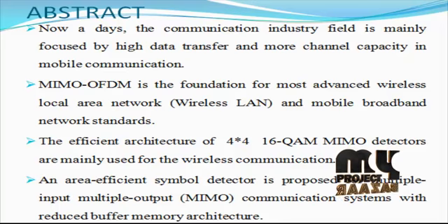Mbps. LTE-Advanced, which is the evolution of LTE, supports single user spatial multiplexing of up to 8 layers in the downlink and 4 layers in the uplink, targeted to achieve peak data rates of 1 gigabit per second and 500 Mbps respectively. SC-FDMA utilizes a discrete Fourier transform spread OFDM modulation with similar performance compared to OFDM.